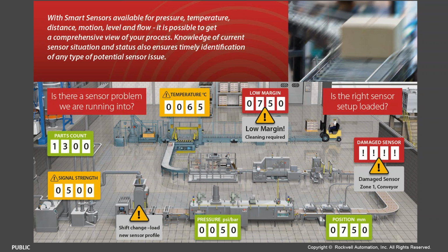Now with an IO-Link enabled registration mark sensor, all the required configurations are taught during commissioning and then stored in the controller. Whenever the label or web is changed, the appropriate sensor configuration for the new label is pushed down to the sensor from the controller. So no one needs to manually teach the sensor for simple label changeovers. These are great benefits that sensors can offer on IO-Link.